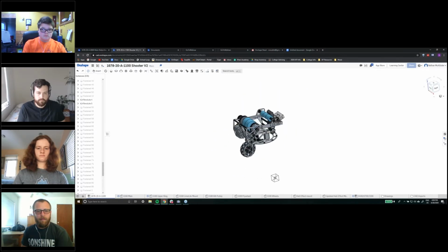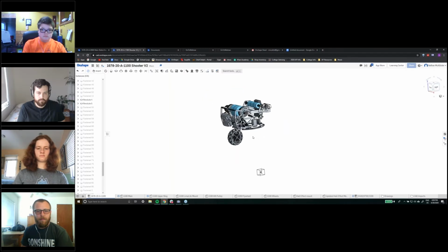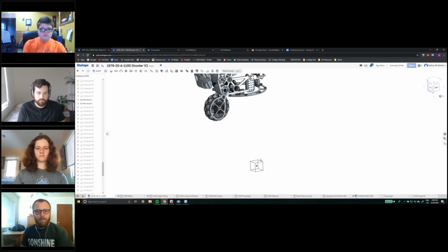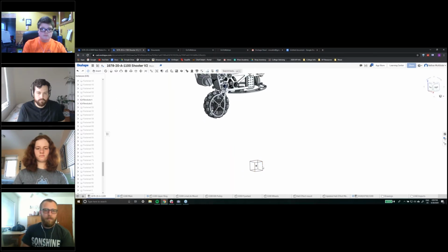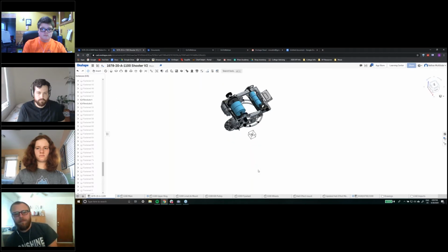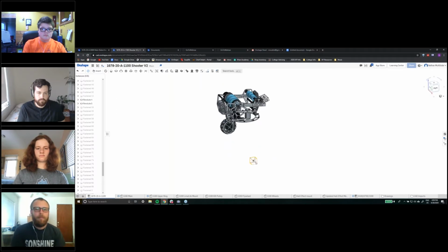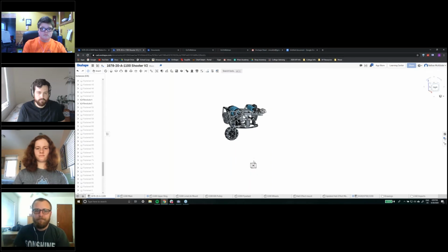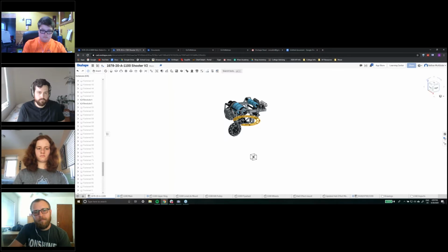And the way we try to manage the integration of all of them is, at least for all the assemblies I designed, I put this clear box at the bottom in the middle, where the middle of the robot would be on the ground, so that when we put everything into the top level assembly, we just made all the boxes together and then we're good to go. That's how the integration worked this time. And then obviously you have to do some separate initial geometry sketches for each thing you do, just to make sure everything carries over between documents, but it wasn't too much of a hassle. Yeah, that's pretty much it.